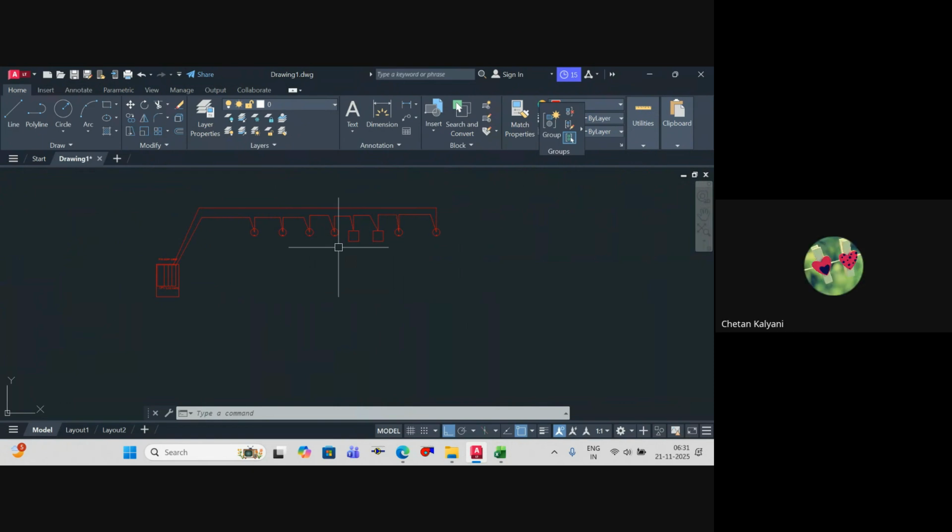So where will we locate this panel? It's not mandatory, but generally we place it near the security. In smaller offices, we'll place it in security rooms. It could be a guard room, or near the reception table or reception counter, where generally people will be there and basic training can be given to anyone. But in bigger projects, we'll install it in BMS rooms, where anyway you have continuous people to monitor the entire building management. Understood?